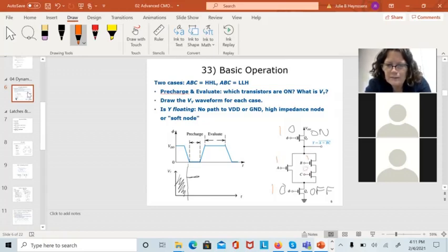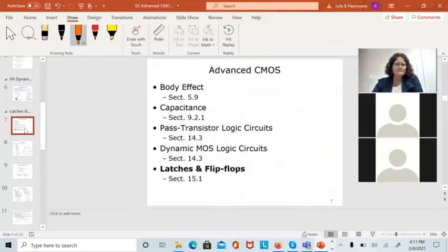So in this case, I have a low resistance path through A and the phi transistor to ground. So then the node will get pulled down and evaluate. That looks an awful lot like many of my exam questions that I've ever written on dynamic logic.